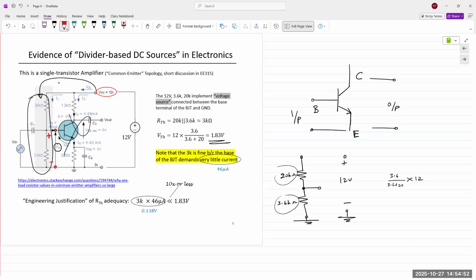Yes. That is correct. I had never thought of that, but yes. We could put an LED in there, it would turn on. But then the LED would sink a lot of the current, so then the transistor may not work.